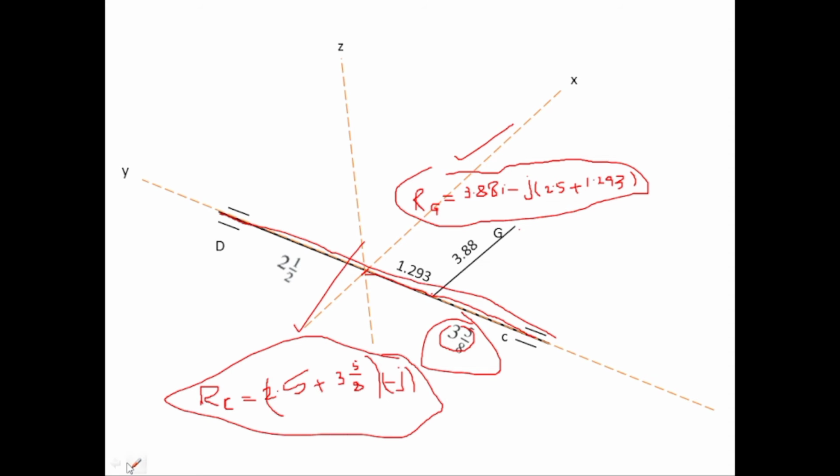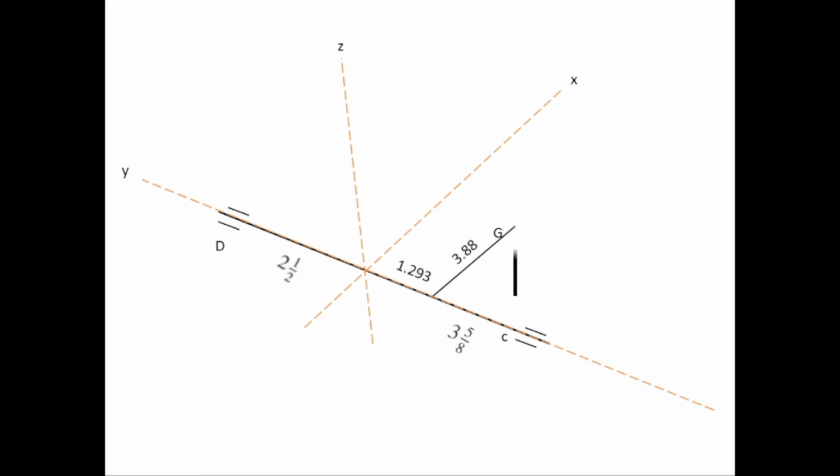Now draw the forces at point G. Since we already talked about the tangential component, that it will be in positive z direction, let's draw it in positive z direction. The axial component WA will be in negative y direction because C is actually taking the thrust load. WR is in a radial direction, or negative x direction. There will be reactions at bearings D and C, which will be taken by them, so show them as well.